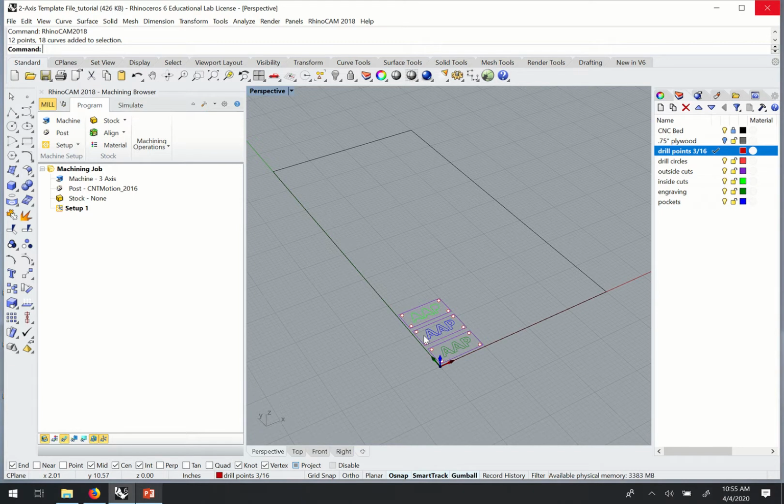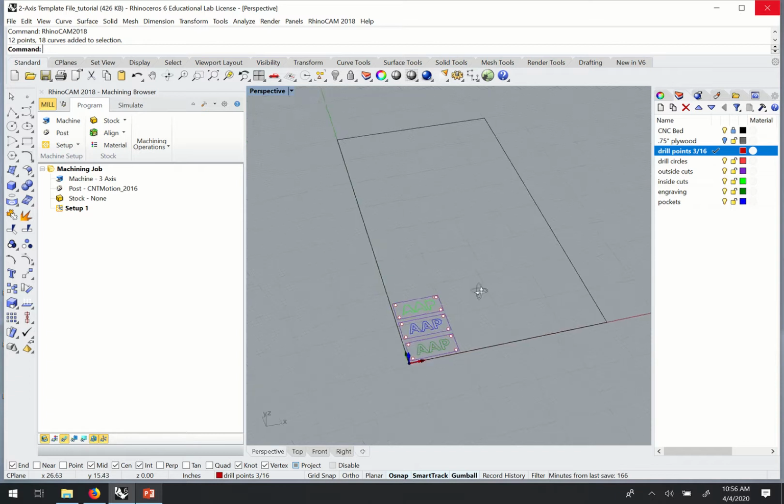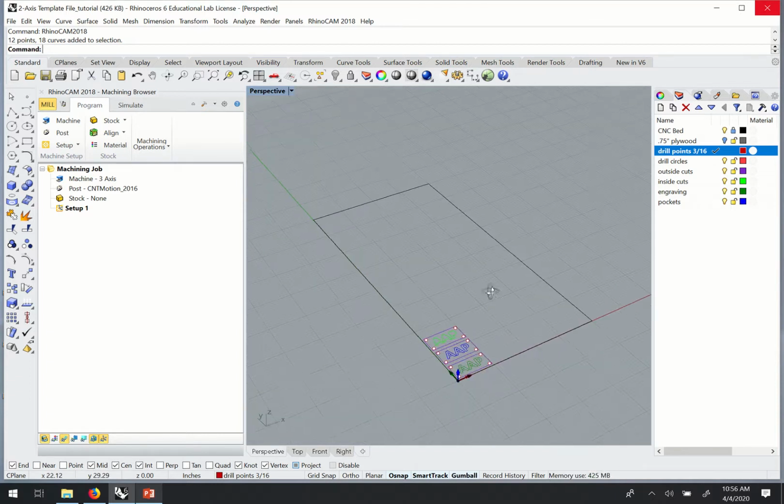We often start with a very large model, whether it's a building or a site model, and we're making a lot of changes to that, and ultimately you might have copies of things, and you should get rid of all of that and just export only the geometry that you want to use to CNC. If you have a lot of other geometry in the file, it can clutter things up and cause some really weird issues.